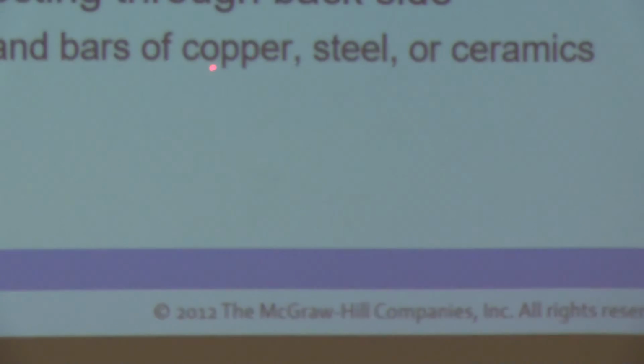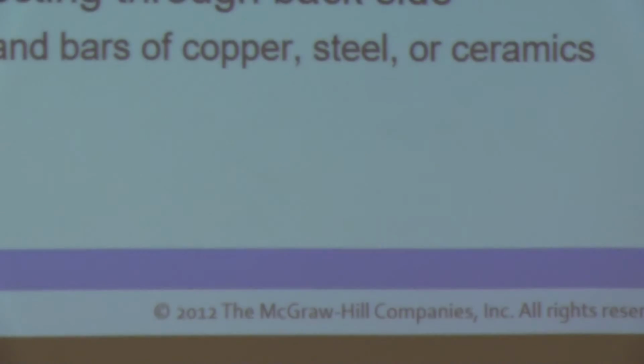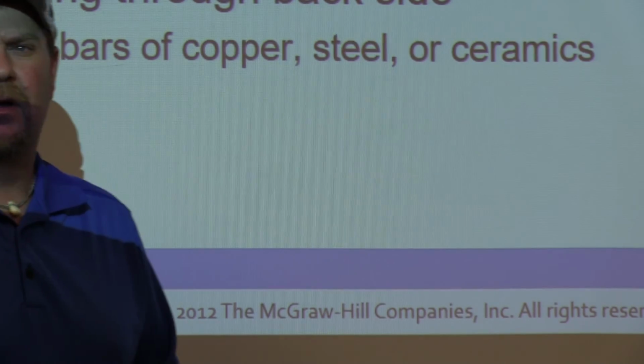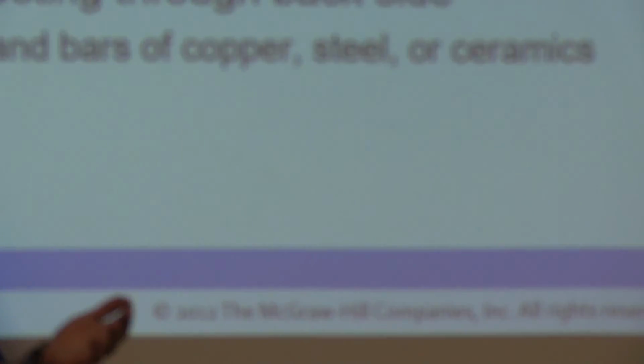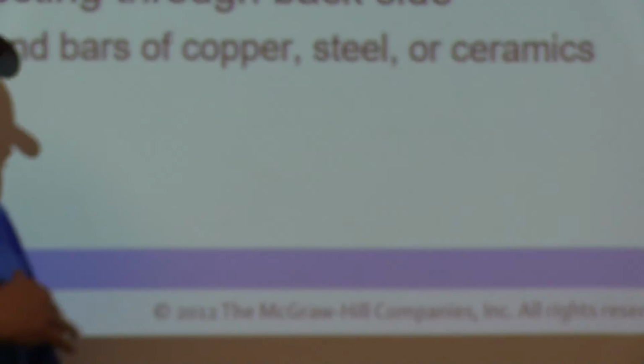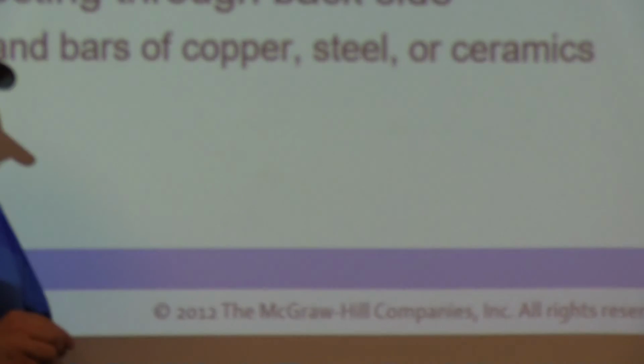So we talk here of backing up to prevent weld from projecting through the backside. You can use copper, copper's a really good one, or brass specifically. I used to have a big brass plate that I machined up to where it's a flat face, drilled and tapped it with a threaded handle on that.